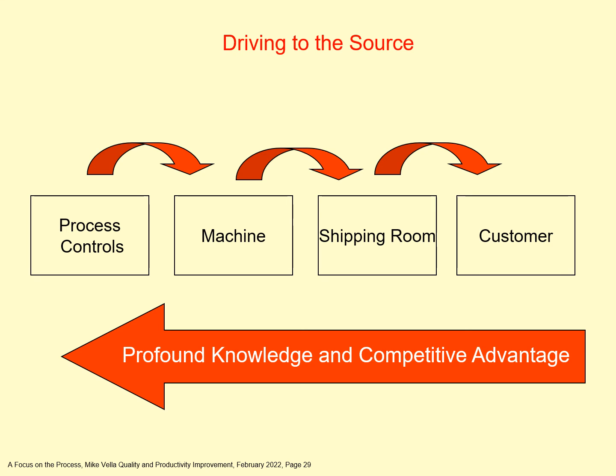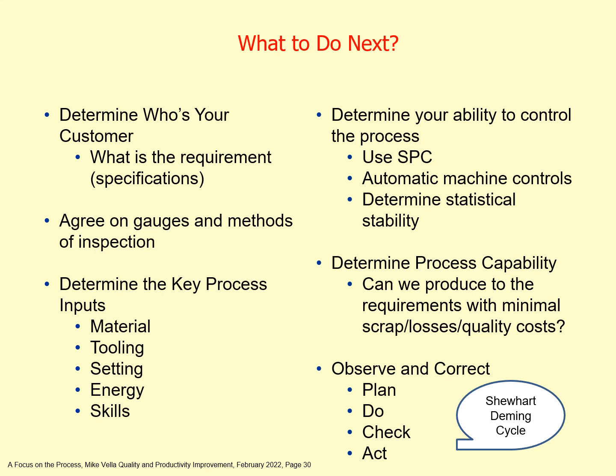That barrel temperature was too low. That speed was too slow. If you understand where each of those process variables was in its setting, whether it was optimum, high or low, then you'll understand how those affect the process and eventually affect the product. That's profound knowledge.